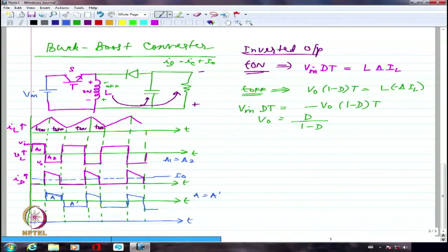So, if I am looking at how really the capacitance voltage is increasing and decreasing, whenever I am getting a current from the diode which is charging the capacitor, I am going to probably have increase in the capacitance voltage. Whenever it is discharging to the load, it is going to decrease, and so on and so forth. This is how it will be. So this will be VC, whereas this will be IC.